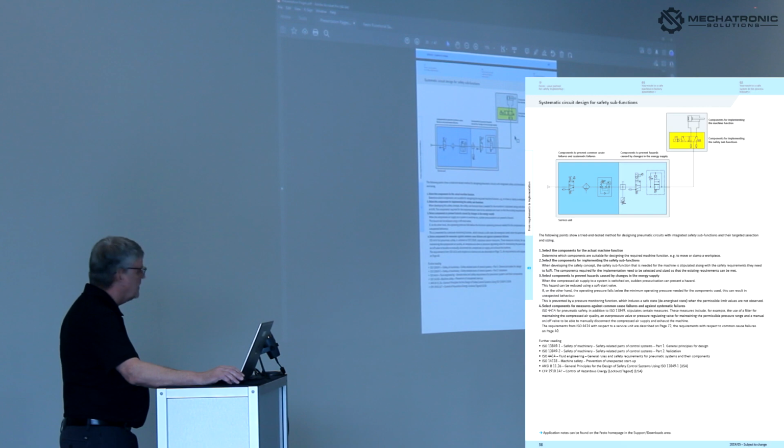Here's just a little diagram of an air prep going out to an actuator. What you've got is a manual shut off here, a filter here, a regulator right here, a pressure switch here, a dump valve which looks like a single solenoid on that one, and this unit right here is a soft start.